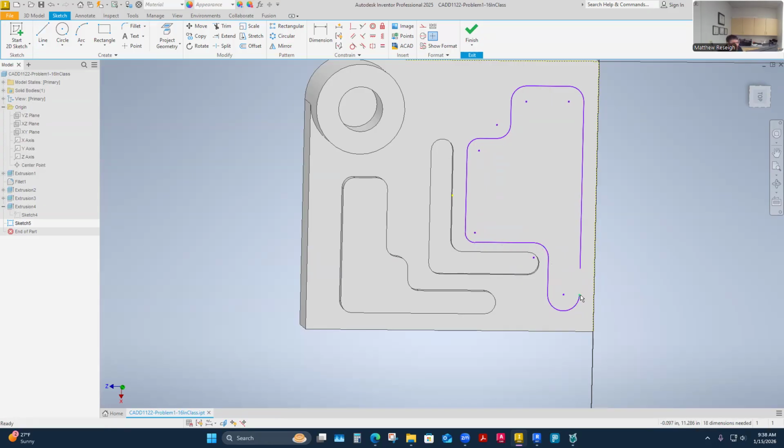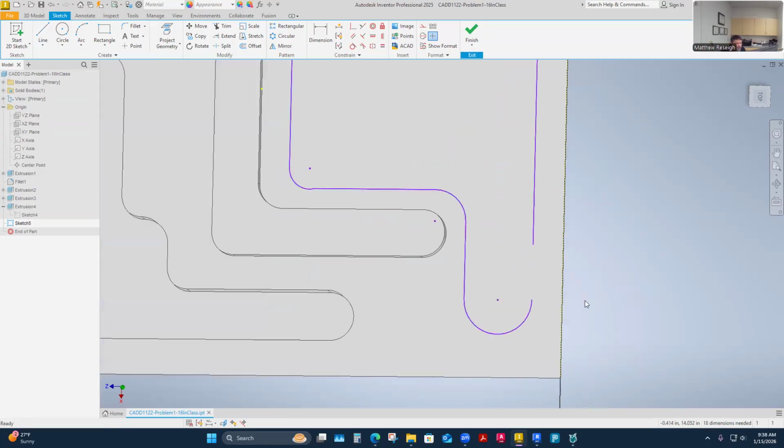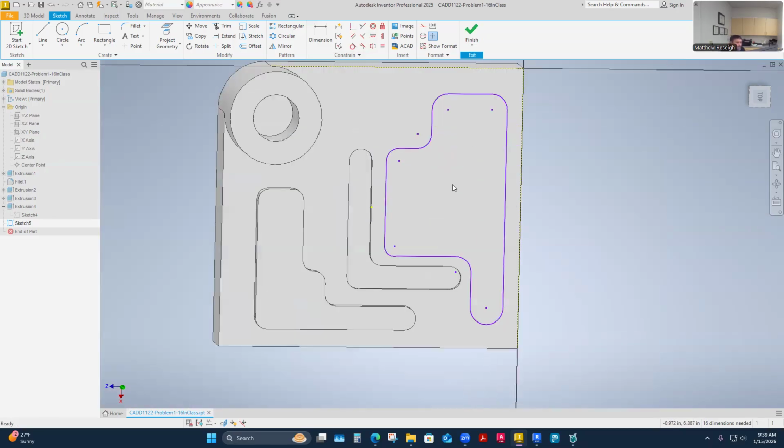And then what I'm going to do, instead of doing another line segment, is this: this is where you could have ended up, maybe this is how you guys have been ending up with a line and a line. I can click and drag these from these end grips here. I could click and drag this together. So in the event that you feel like you have to add an extra line, you could just escape the line command and grab the grips like you would in CAD and pull them together, or you could use a coincident constraint to drive them together. But that's my rough shape.